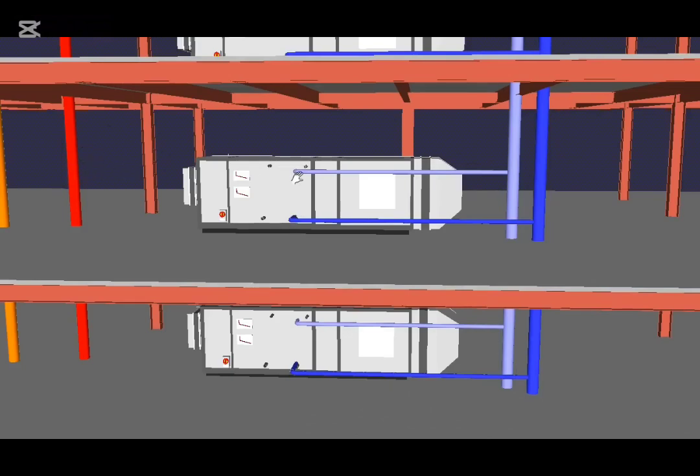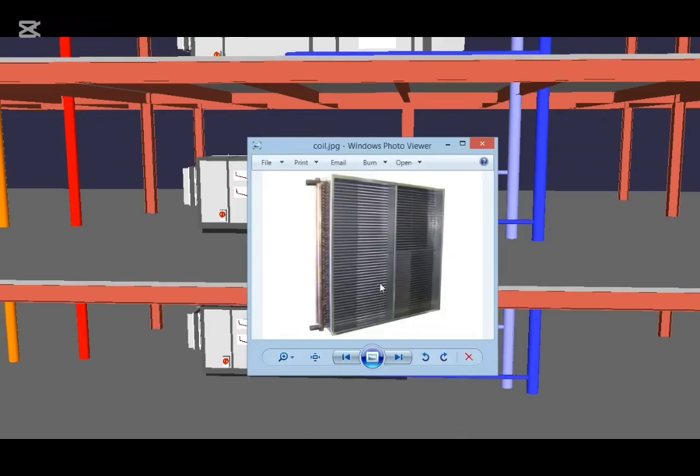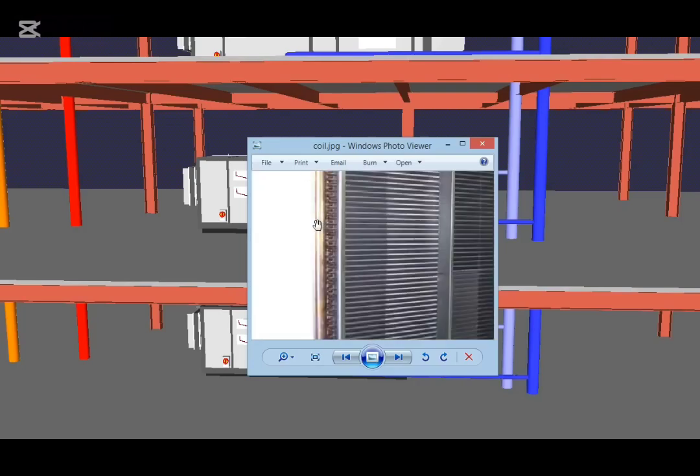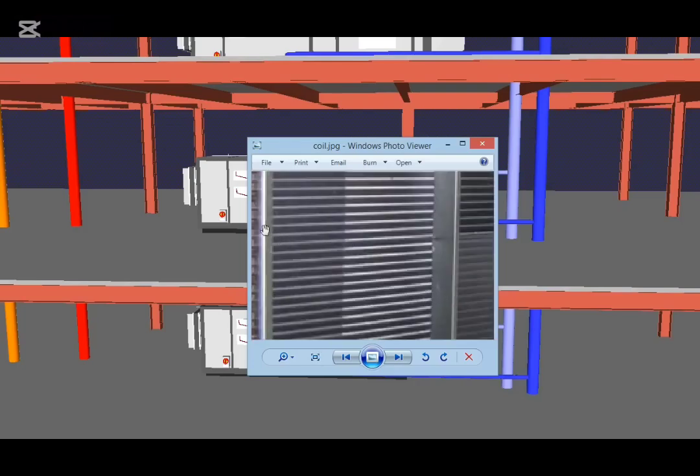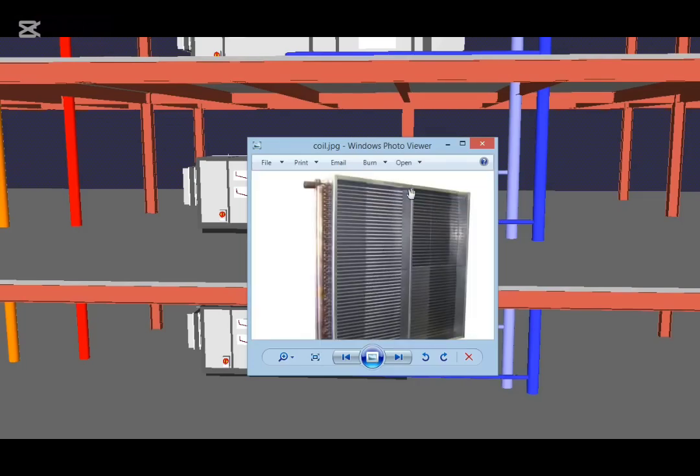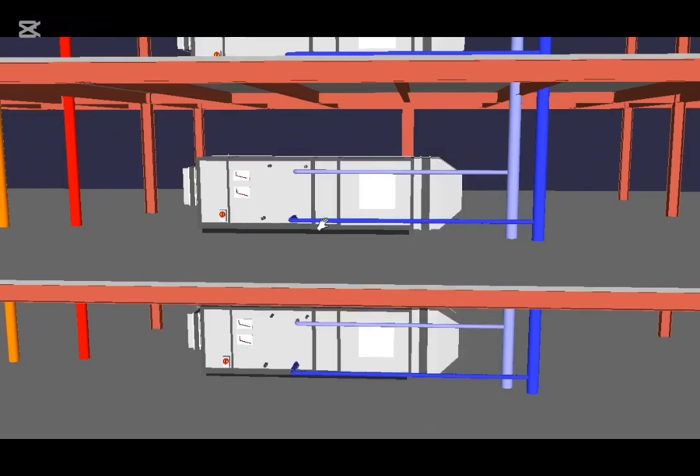And inside this air handling unit is a coil, and the coil will look something like this in the real world. Chilled water enters the coil and makes its way up through all these little loops here, and then back out the top here. So that enters at about 8 degrees in this example, and by the time it reaches the top there, it'll leave that cooling coil at about 14 degrees.